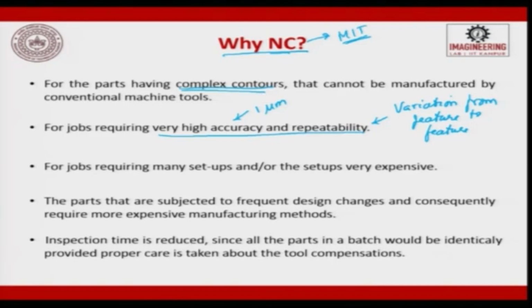For parts that are subjected to frequent design changes and consequently require more expensive manufacturing methods, we always go for NC. This is very, very important. Why? Because today people look at mass customization. So, there is a frequent design change in the part to meet the customer requirement. So, frequent design change and consequently more expensive manufacturing methods are used, where we always go for NC.